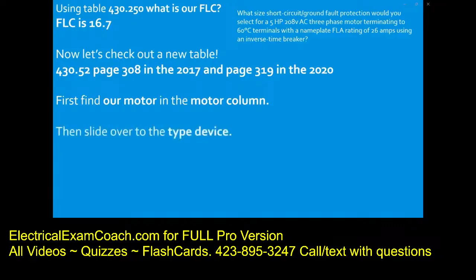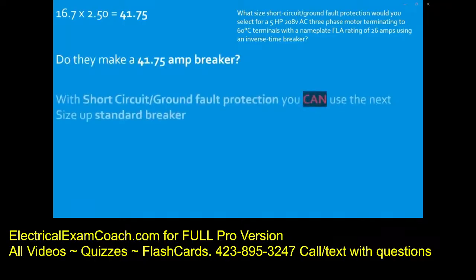Now what we do is we take that multiplier and do the math. We take our FLC, which is 16.7. We multiply it by 2.50. That is going to give us a new amperage to size our breaker by of 41.75. All right, so we did our math. Now, do they make a 41.75 amp breaker? And the answer is no.